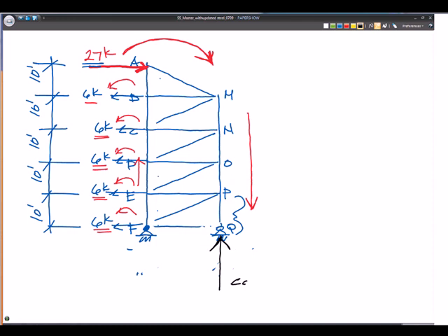This side is in compression. So my initial assumption now isn't just an arrow direction of going up. It's saying that if the ground is pushing back, then PQ is going to be in compression. Okay? That's why you have to understand whether you're looking at tension or compression. Okay, so what we do then is let's take moments about F.